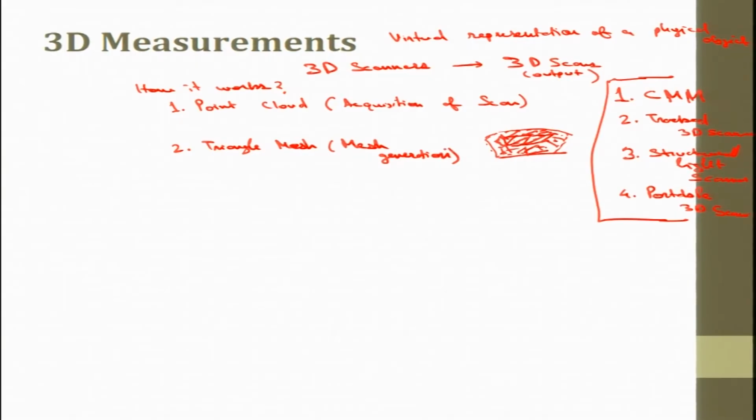The third step, when the mesh is generated, is that we need to optimize the mesh. When we conduct strength analysis or heat analysis, this is the mesh. The more triangles there are, the more computation is needed, so it depends upon what type of computation we need to do. So we optimize the mesh to reduce the computation time and to get the optimum shape as well.